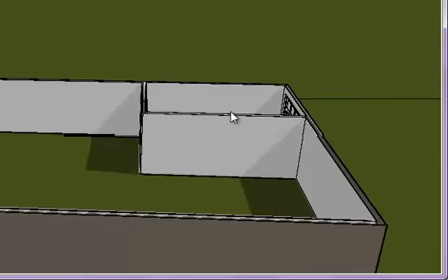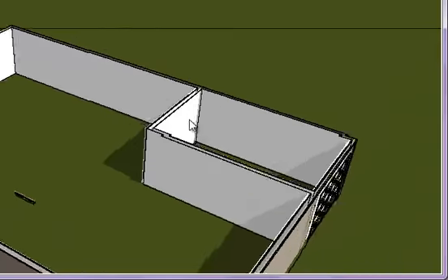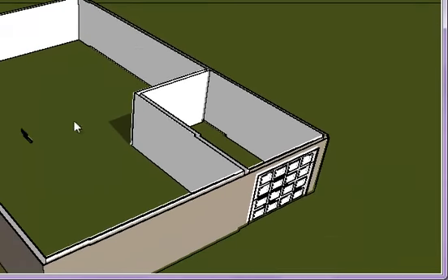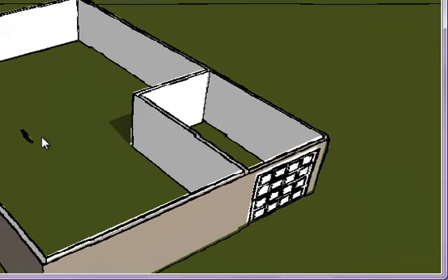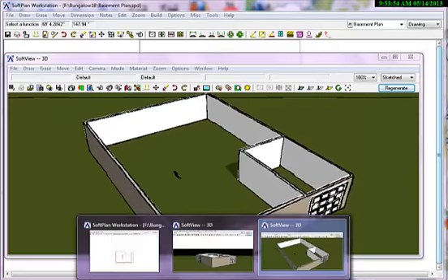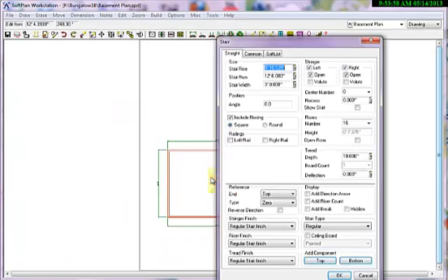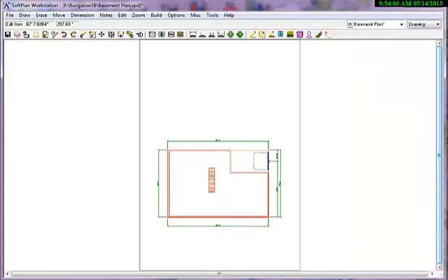So all of my walls have changed, and notice that my stairs are actually going the wrong way because they're still going down. I'm going to need to change that later, but I'll do that in a little while. Okay. In fact, the easiest place to do that is in the floor plan. So I'm going to go back to the floor plan, do Edit, Edit on the stairs. I now want the bottom to be at 0. Now if I say OK and go back to